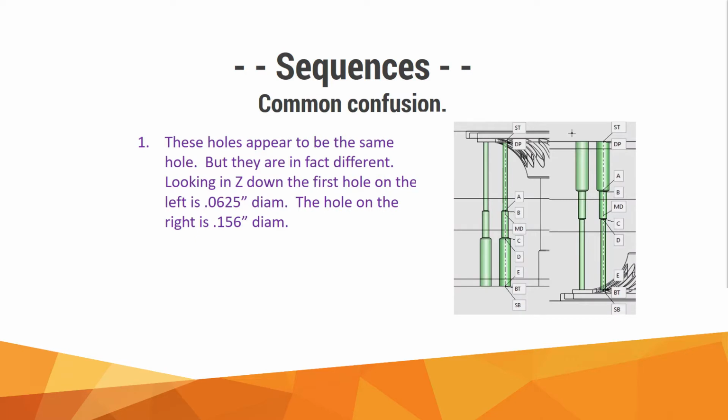One of the common confusions, just something to fit in your head right at the very beginning, is how auto drill looks at holes. In this picture, you can see these two holes appear to be identical, but really they're different. There are different UCSs, one's pointing up, one's pointing down, and because of that, we see these seemingly similar holes facing different directions.